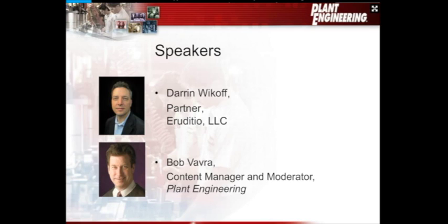Okay, so again, I'm going to examine spare part stocking strategies for assets that, as a result of the criticality analysis, indicate that spares lead time is an issue. That's the first way I want to answer that. Just because there's a customer impact or a regulatory impact doesn't necessarily mean that the criticality analysis result is pointing to spare parts as a strategy. So let's be very careful with that one.